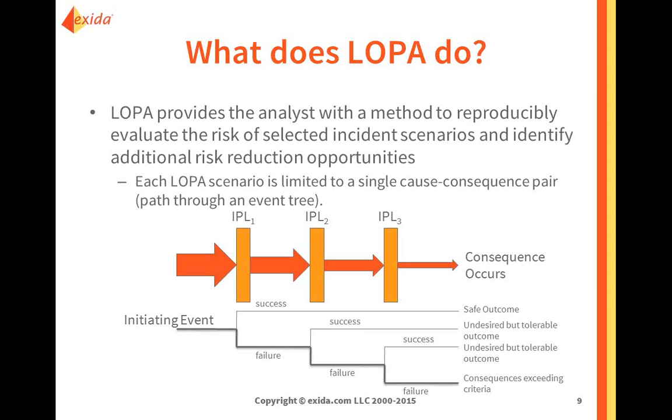So if on average a control function fails once every 10 years, you typically are not blowing up boilers once every 10 years. But why does that happen? There may be layers of protection. The control function may still fail once every 10 years, but an operator may take an action, or you may have a relief valve, and so on.